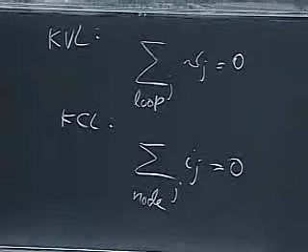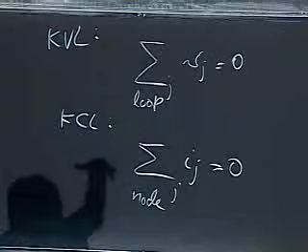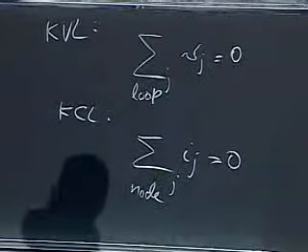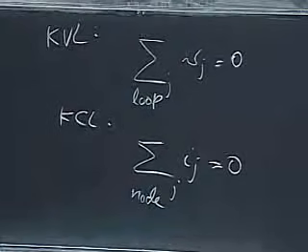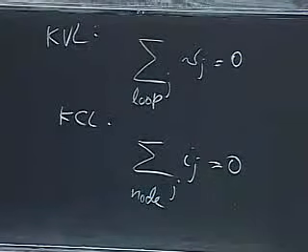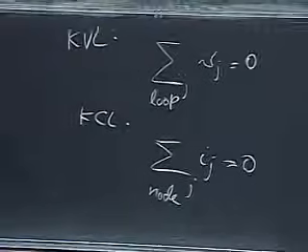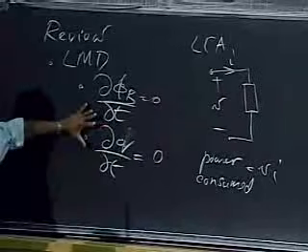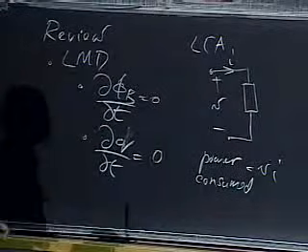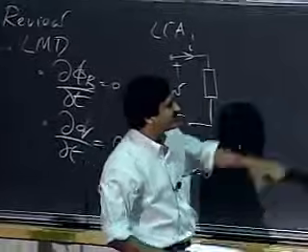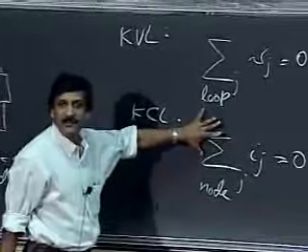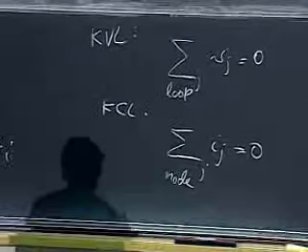Okay, so if I take any node of a circuit and sum up all the currents coming into that node, they will all net sum to 0. So notice that what I've done is, by this discipline, by this constraint I imposed on myself, I was able to make this incredible leap from Maxwell's equations to these really, really simple algebraic equations, KVL and KCL.